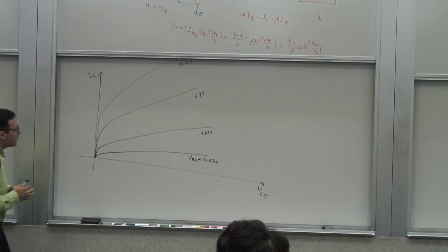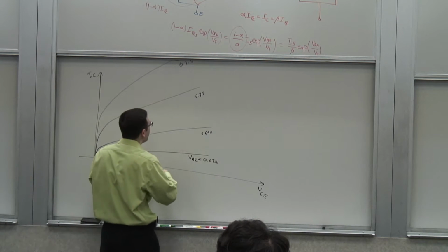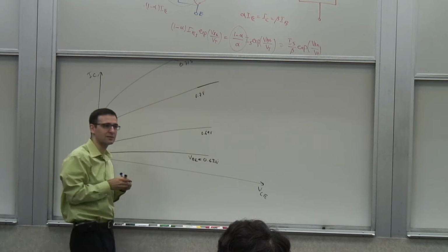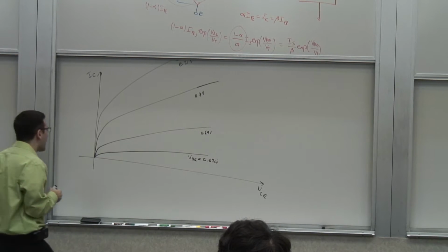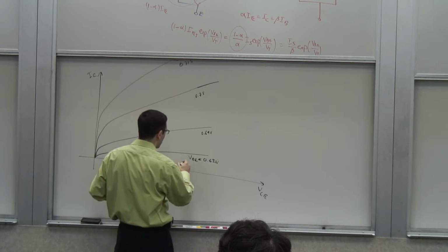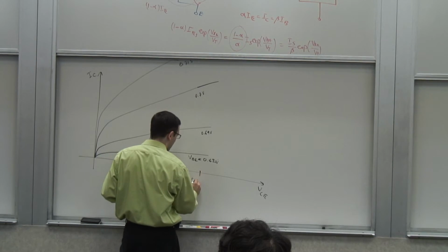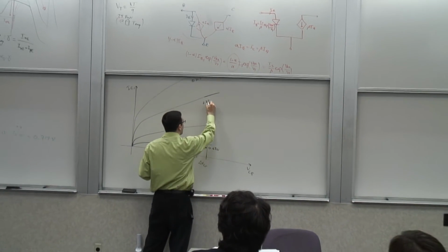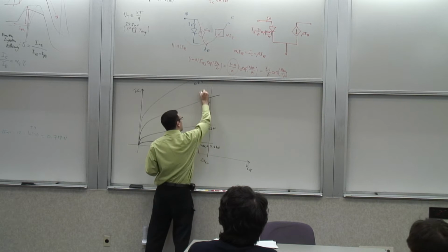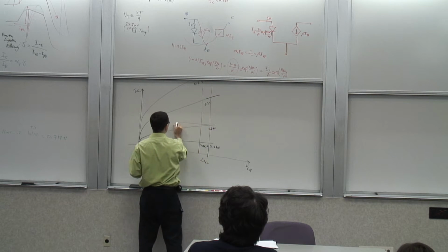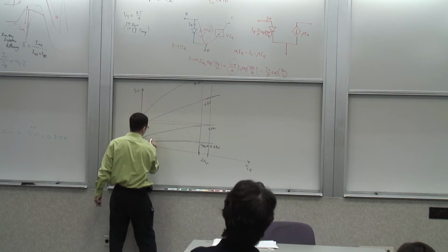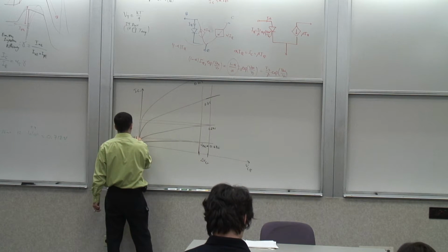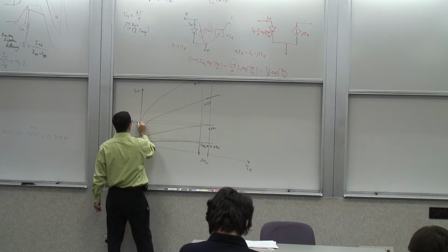But what I want you to pay attention to is the other aspect of this, that these are not exactly constants. This is true about any transistor, pretty much. They grow with the current, right? So if you look at it, what you notice is that for a given change, let's say delta VCE, there is a change in the collector current, delta IC. That of course increases with the current itself. So there's a delta IC that's proportional to IC.